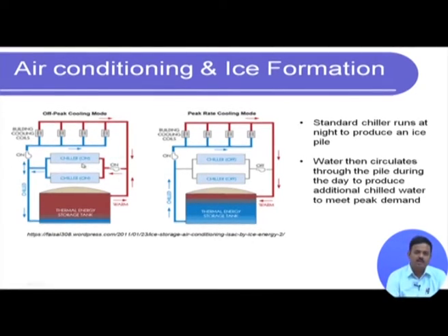Okay. So, now let us look at this. We have a chiller unit, two chiller units, let us say, working in parallel, and which is producing chilled water. So, chilled water, typically what happens is it goes into the building and flows through these different building cooling coils, as they are calling here, which are typically the quote unquote evaporator units that I talked about, through which chilled water flows and air flows on the outer side and it gets cooled. Okay.